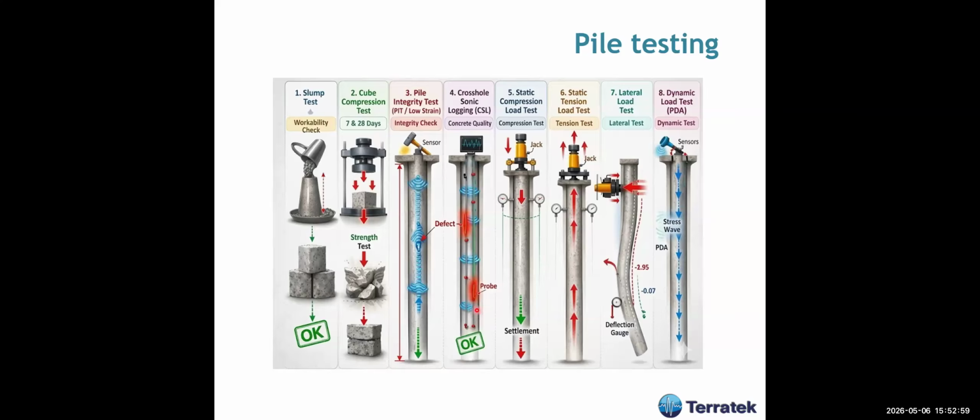Usually when the pile is 2 meters, for every 30 centimeters in diameter, we put one additional pipe. The minimum would be 4, the maximum could be 8 if the diameter is over 2 meters, okay? And then we do sonic tests in order to check for defects. It's a wave that goes from one tube to the other. One is the emitter, the other is the receiver, and then we check the quality of concrete for large diameter piles.